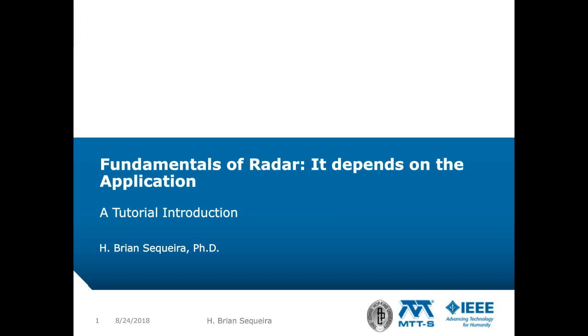Although there are many ways to classify radars, the classification that is germane to this tutorial is that of monostatic and multistatic radars. We adopt the definition that a radar is monostatic if it transmits and receives signals from a common antenna aperture. Usually, the transmitted signal is many orders of magnitude greater than any received echo, and therefore it is not feasible to conduct full duplex radar operations, that is, transmit and receive simultaneously with a single aperture.